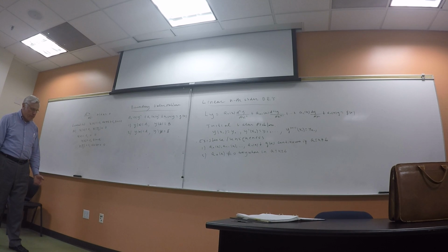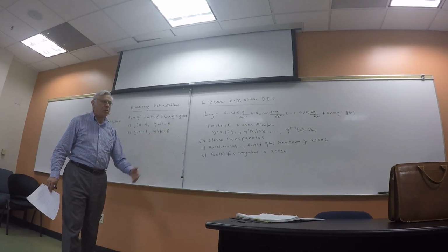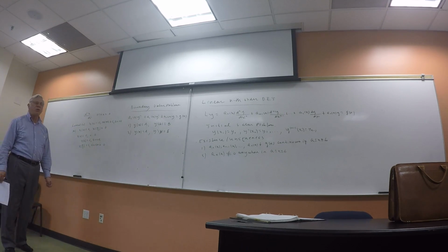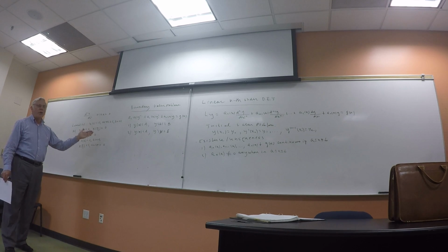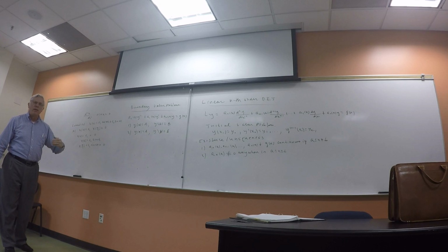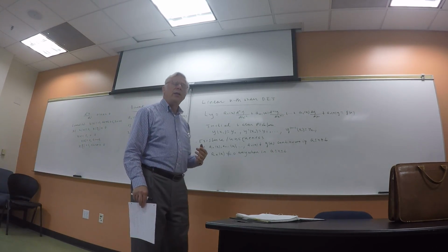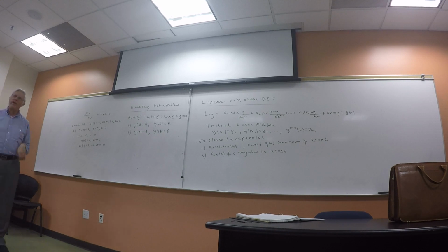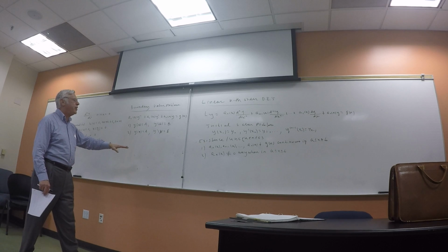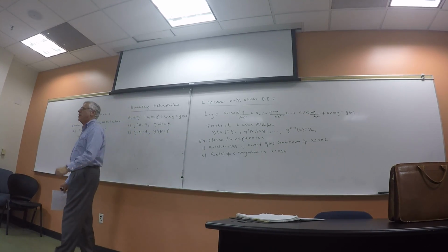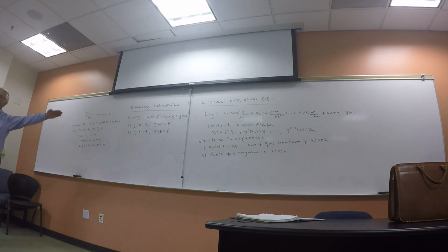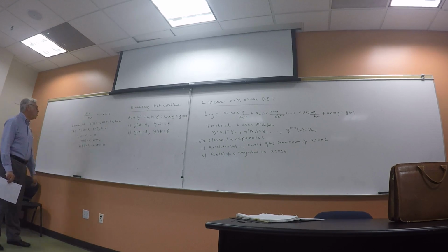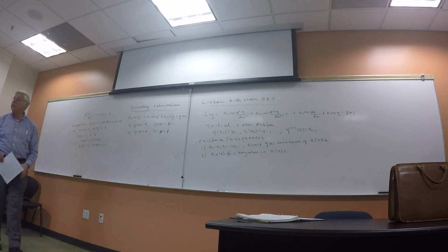Hopefully, though, if you're doing a physical problem and you have the right data, most of the time people don't worry about it. But I can tell you some interesting stories, especially in the history of boundary layers, where people had very complicated equations, boundary value problems, and then they would solve them numerically, and then they would get different results, and then a more careful analysis revealed that the solution wasn't unique. It was some type of slip condition that wasn't accounted for. So these theorems are not just esoteric and of mathematical use. Many times they can be used to check that the solution is unique. When you go to the computer, it's not going to tell you; it'll get one solution depending upon the numerical method it uses. So it's very important to know that before you even go to the computer. So here we have a second order equation, two boundary conditions, non-unique solution, an infinite number of solutions.